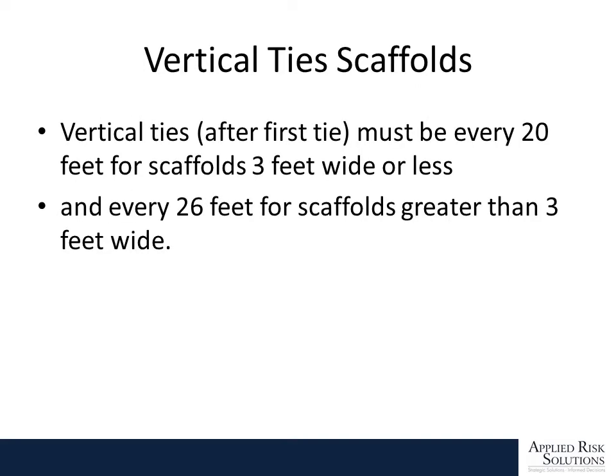Once you tie it in the first time, if the scaffolding is 3 feet wide or less, you must tie it in every 20 feet after that. If your scaffolding is wider than 3 feet, after you tie it in the first time, you have to tie it in every 26 feet after that.